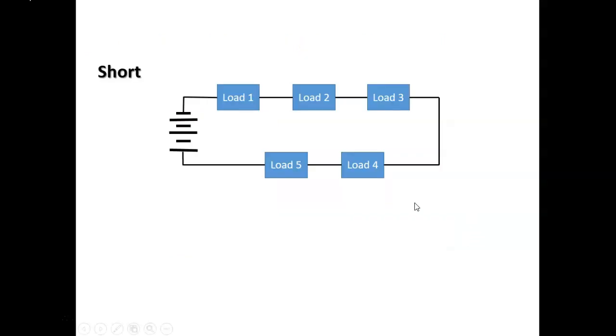All right, so instances of a short. A short is basically where your load goes away. It makes it so there's less resistance. Less resistance means more current, more amperage. This part right here is a short circuit. That's the one you really do not want, because hopefully it will trip your breaker. If it doesn't, you are in some very deep trouble.